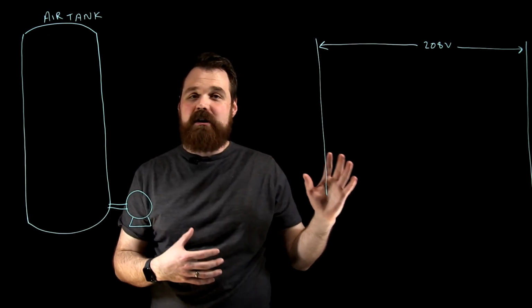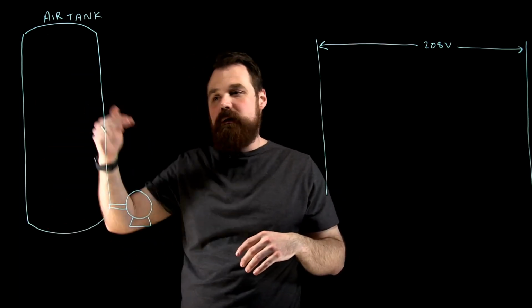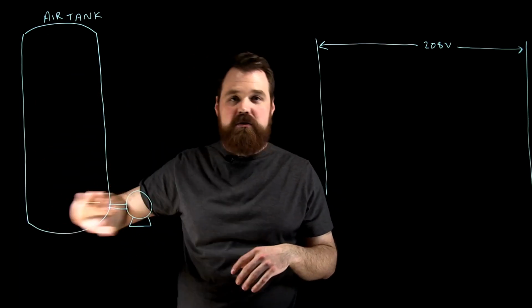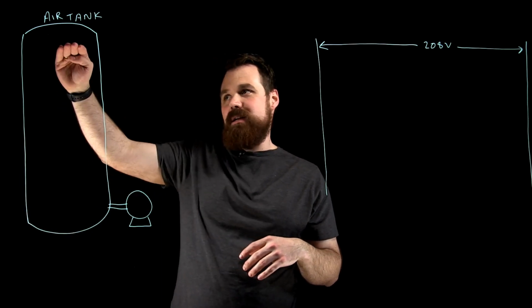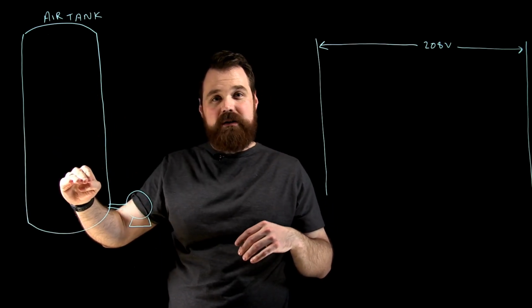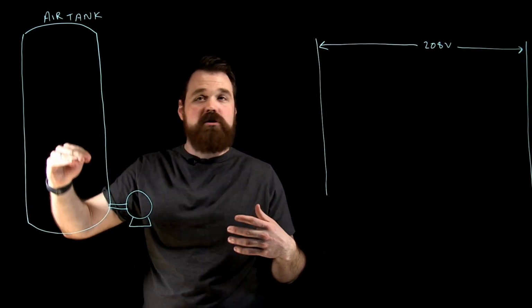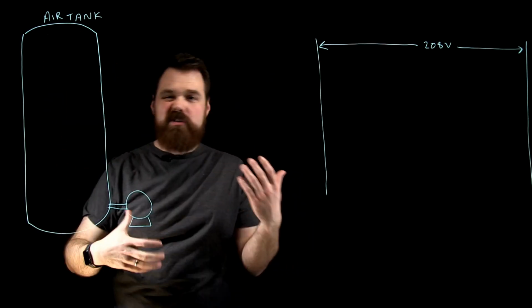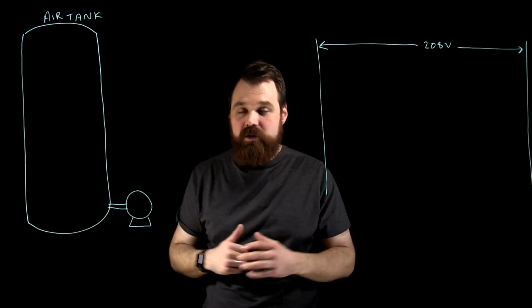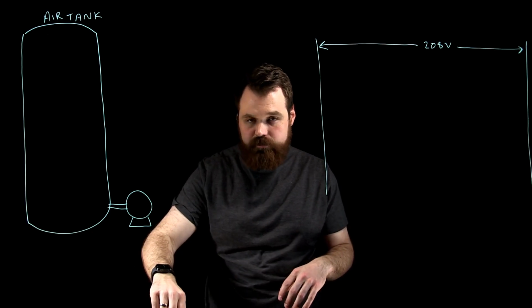We'll use a NEMA contactor just to fill this tank up. In this case, with an air tank, we use the air for whatever purpose. As the air tank comes down, it reaches a certain point, activates a switch, and then it starts to fill up again until it reaches full. Think of your simple air compressor at home; it would work under this same idea as well.